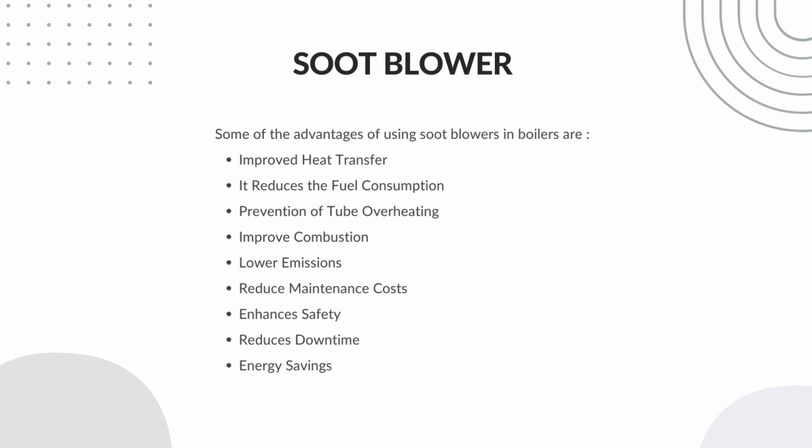Soot blowers help remove these deposits, allowing for better heat transfer and improved boiler efficiency. It reduces the fuel consumption. By enhancing heat transfer, soot blowers help the boiler generate steam more efficiently, which can lead to reduced fuel consumption and lower operating cost.